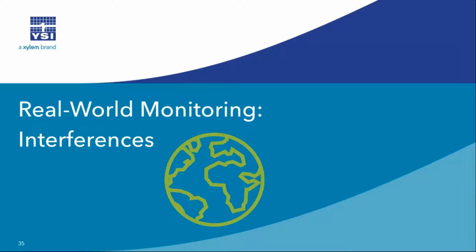All right, I've got another one here from Jessica, and Jessica's asking, since her laboratory does a 1-point calibration with reagent-grade water to zero her probes, is this good enough, or should they be doing 2-point calibrations? They're interested in purely the chlorophyll channel, chlorophyll A readings to be specific. So definitely, initially with a sensor, you should be doing your calibration. You should do the 0 point with the water, which you're doing, but you need to do another point on that. You need to do the 2-point calibration. And the reason is because you're not really calibrating if you're only doing 1 point initially. I think I understood that question right, Brandon? Yep. All right. What else have we got?